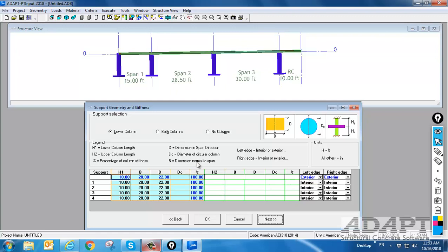We're only going to do bottom supports. You could do top supports. I mean, there's an argument to do top supports when we're checking, for example, service total stress, because if this is just some intermediate floor in the building, you're really going to have probably top columns here. Currently, there's no way to isolate and say for initial stress, check with bottom columns only. For top stress, check with both. So you can tweak stiffness. You can turn columns off and on in terms of this input to check one versus the other, but it requires 2 runs in order to do that.